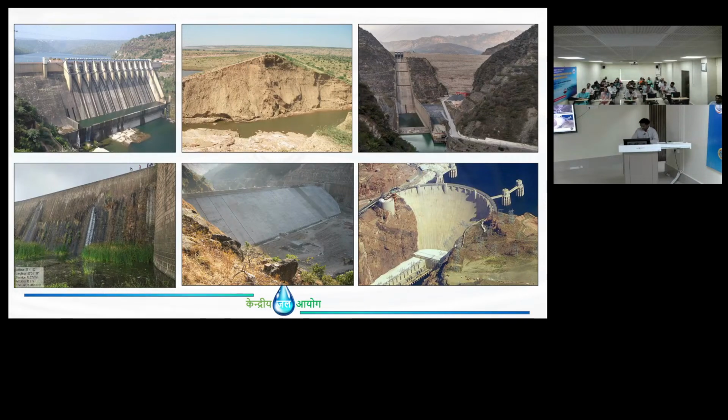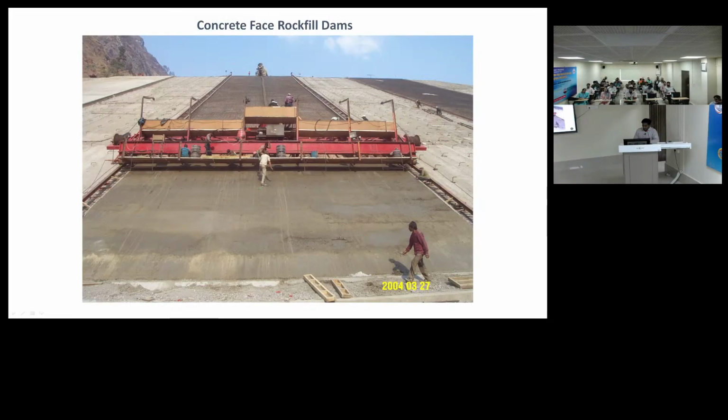Now we will see the names. As everybody already told: concrete and earthfill dams, rockfill dams, masonry dams, concrete face rockfill dams, and arch dams. In India we have only 1 or 2 arch dams, because arch dam design is a big issue, and second, we should have strong abutments for arch dams. A concrete face rockfill dam is like a rockfill dam, but on the upstream face they will have concrete layers, a concrete panel.